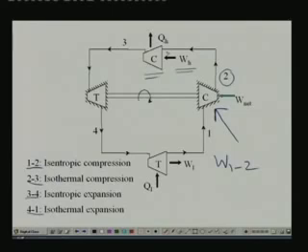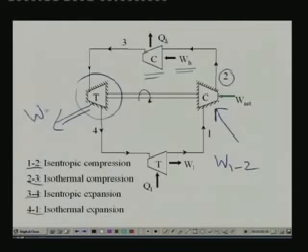Okay. And process 3 to 4 is taking place in an isentropic turbine. So, during this process it gives out a work output. This is the work output from the turbine, and this is, as I said, an isentropic process. During this process its pressure, temperature and enthalpy everything reduces. So, the enthalpy, temperature and pressure at point 4 will be lower than at point 3.